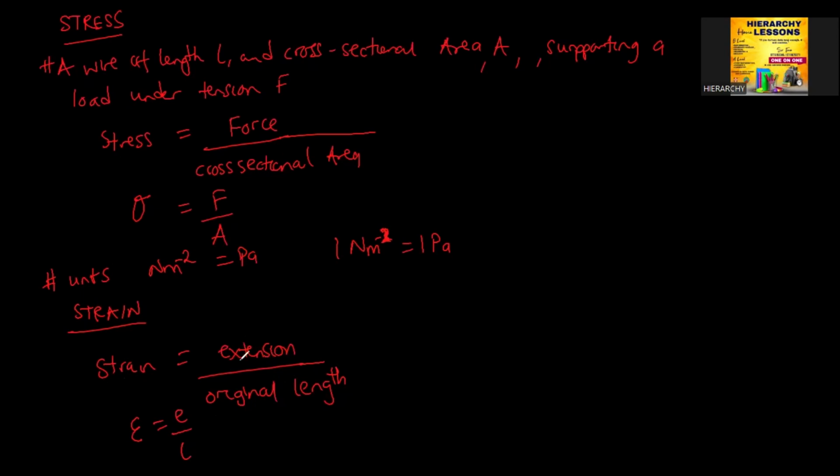So strain is a ratio. Remember, it's length over length, so it has no units, since it's a ratio. So we've looked at stress, we've looked at strain. Now I want to look at what we call Young's modulus.